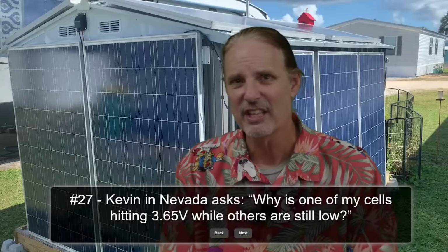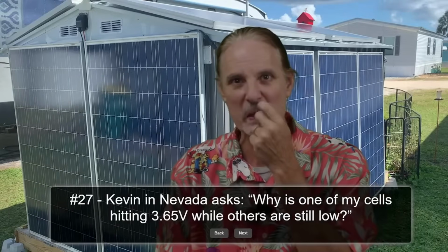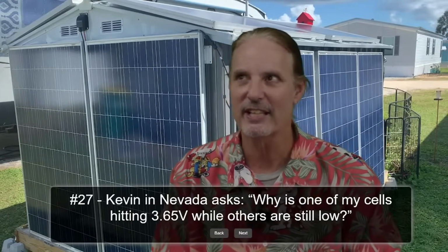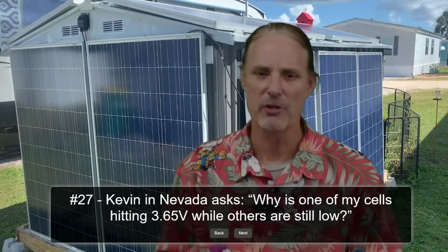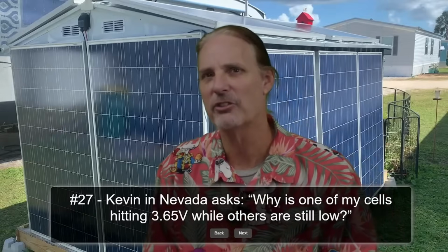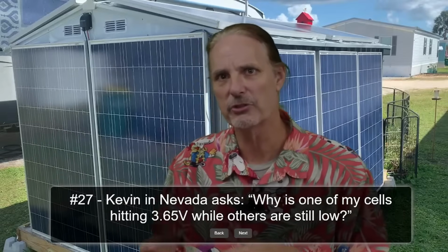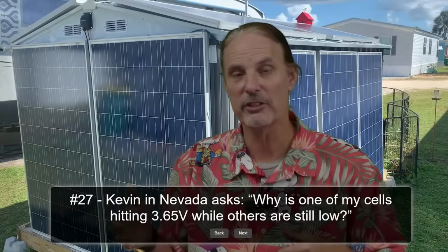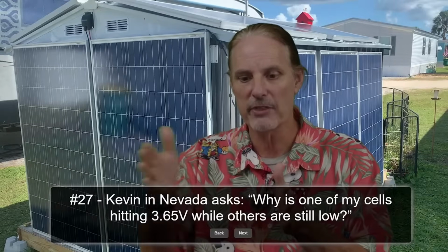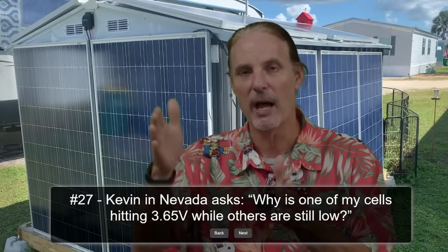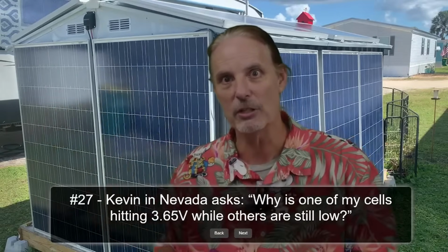And this really is going to take them a few more years of building balancers where you can say things like charge to 58 volts, and the BMS is smart enough to know that I need to slow down as I start approaching the 55 and 56 range in order to give those cells enough time to balance, and hopefully some AI logic in there that would say, look, based on the rate that I'm charging and discharging, I'm going to have 30 or 40 minutes of this kind of sun, and I need to do this or I need to do that.